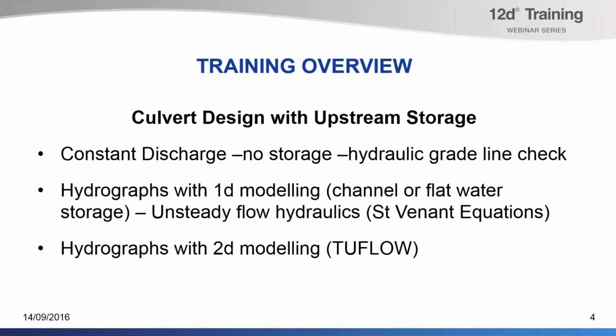After we've done a fairly good look at the 1D modeling, we'll move on and take a look at 2D modeling using the TUFLOW engine. In this case, we'll use the same hydraulics to calculate the flow through the culverts, but we'll use a 2D engine to calculate the water levels upstream and hence the storage upstream of the culvert. So let's jump into 12D and start taking a look at a project.